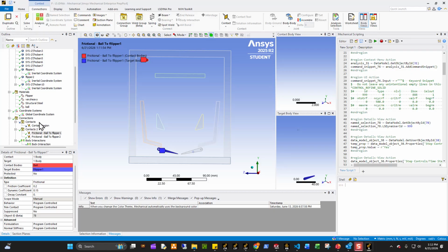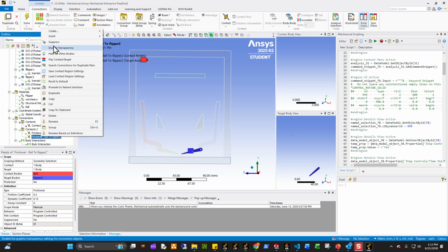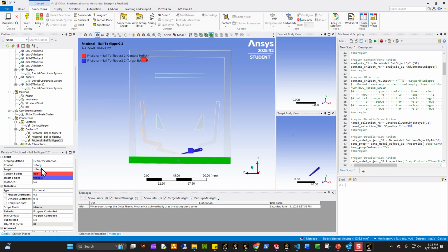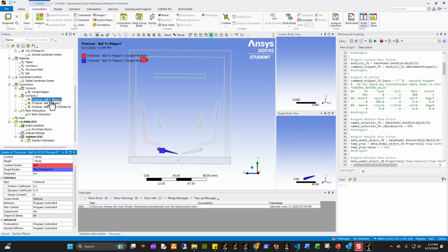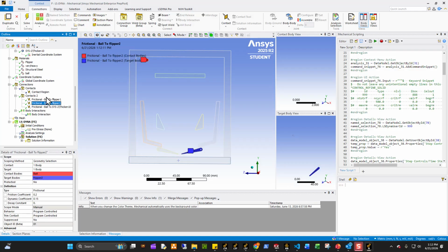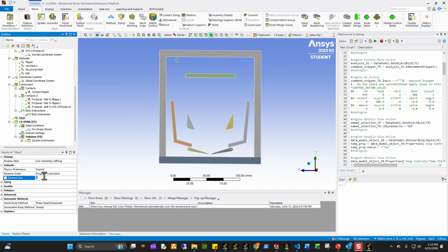And then the last thing, of course, I want to set up a frictional contact between the ball and the bottom surface, right? And this has an ID of 84. These three right here are going to be things I'm gonna use as a target of the sensor to activate certain aspects of the sensor. Okay. All right. The rest of it is that I'm going to basically mesh this thing with a 2mm mesh. Keep this thing super simple.